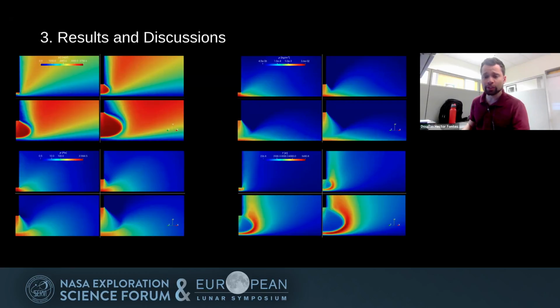The rocket plume temperature indicates the local level of agitation of molecules that influences how they transfer momentum to a particle. As we can see in the boundary layer and in the shock wave, the molecules are more energetic, which allows more momentum transfer from the flow to the particles of the regolith.